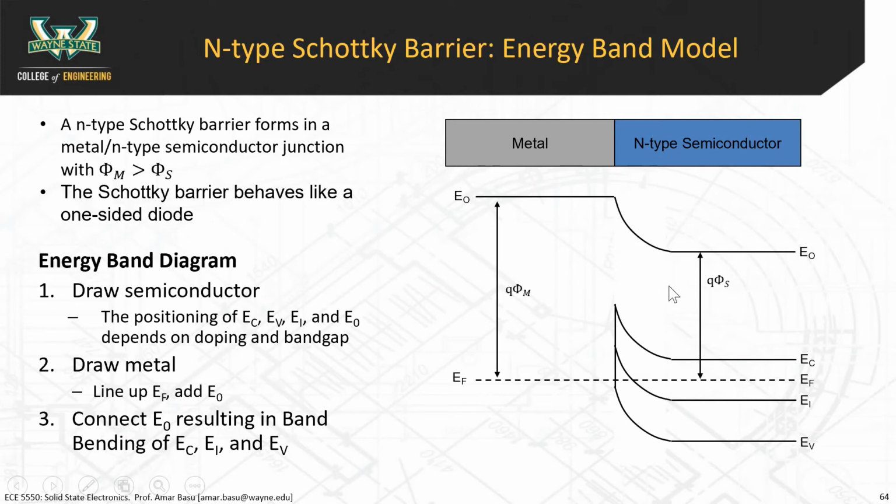All right, now you might be wondering, why isn't it curvy on both ends? If you remember in the PN junction, there was curvature on this side of the diagram as well. But in the metal semiconductor junction, there's only curvature on this side of the diagram. This is because of the way that metal forms an interface with the semiconductor.